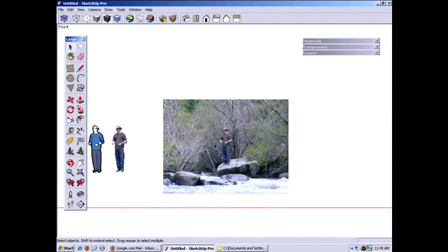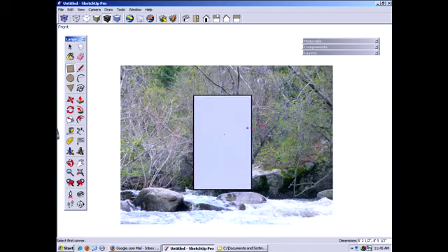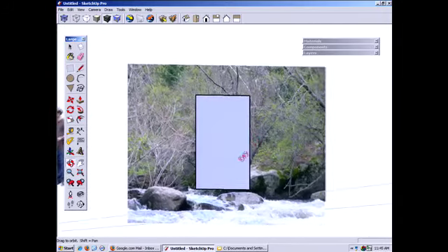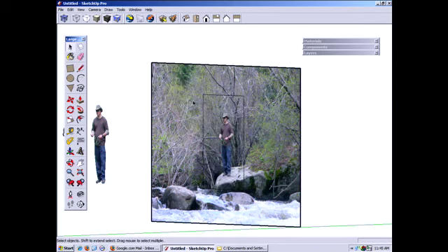What I did do is, and this works for any type of geometry, let's just draw a rectangle over that surface, right? If I right-click on the image itself and choose Explode, that image, which was sort of grouped, is now exploded, which means it merges with the geometry that was also on top of it.